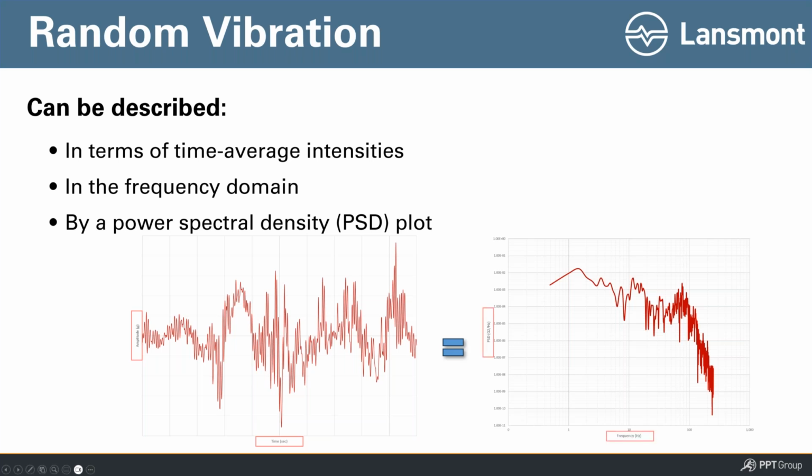And so now, if I highlight the axes here, we have something called PSD, which the units are G squared per hertz, which you can have a whole discussion on understanding what that term means. But in the simplest of terms, it means intensity, right? It's amplitude. So it's not acceleration, but it's a form of power or acceleration on the y-axis.